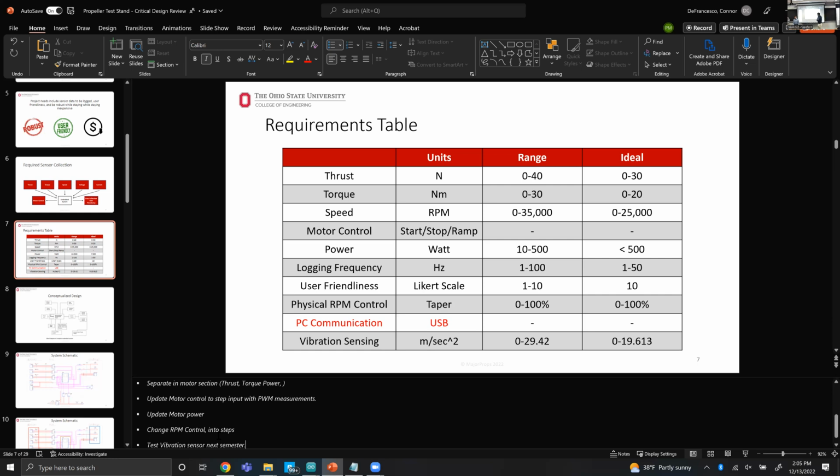And the skill of how to troubleshoot, how to trace and see everything is connected. Finding that RX was connected to RX was the biggest challenge, and they figured it out. How do you check those? Those are the skills that you need to have. I'm recording all this, it was great. So next time, they'll ask, is RX connected to RX?